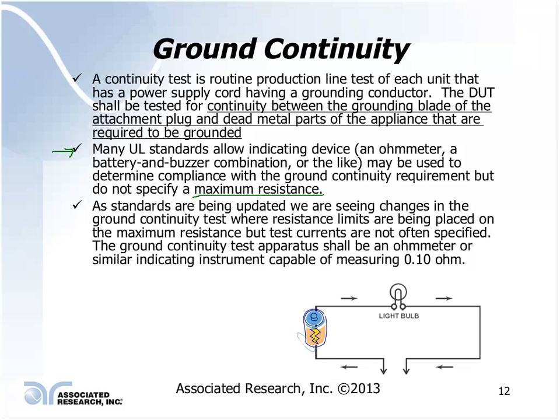You could have one strand of your wire making contact and still pass a simple continuity test, because this is not a high current test. It is not testing for a maximum resistance of this ground circuit. Okay, so a continuity test is in fact better than not testing at all, but it is not necessarily the best test to make sure that that ground conductor is intact.